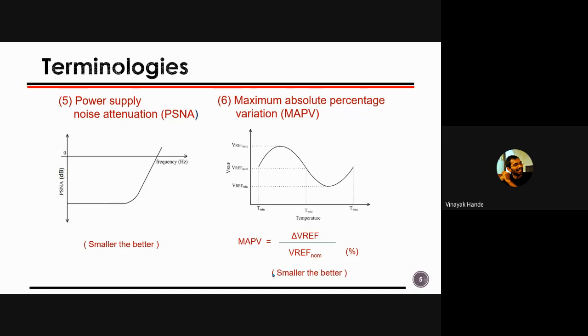It's the noise of the voltage reference, because noise is also one of the critical points while designing a voltage reference, particularly if you are designing a voltage reference for high resolution data converters. Like if you go for more than 16-bit, which nowadays is quite normal. But if you wanted to go beyond 16-bit resolution data converters and you are using the reference voltage, then definitely you have to think about flicker as well as thermal noise. So I did not talk about this.